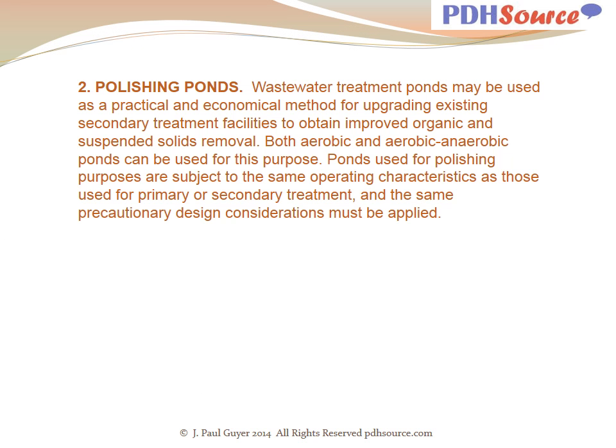The first method that might be employed is polishing ponds. Wastewater treatment ponds may be used as a practical and economical method for upgrading existing secondary treatment facilities to obtain improved organic and suspended solids removal. Both aerobic and anaerobic ponds can be used for this purpose. Aerobic, of course, indicating in the presence of oxygen, anaerobic indicating in the absence of oxygen.